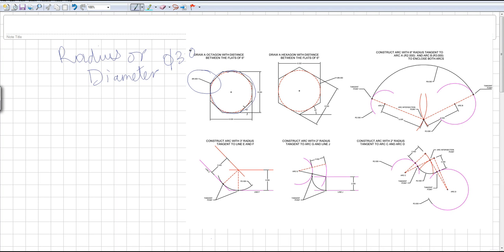3.0, right? So the symbol for the diameter is always drawn as a circle, and then you put a slash like an angle, right? So this is the symbol for the diameter, and the symbol for the radius, which you would see somewhere. Let's see, where's the radius?